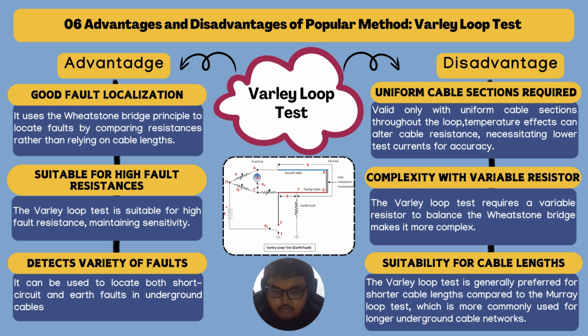The method had good fault localization, where we can locate the fault by comparing the resistance, despite relying on the cable length itself. The next one is the Varley loop test is suitable for high fault resistance that can maintain the sensitivity. And the last one is the Varley loop test can be used to locate two faults, which is short circuit fault and the earth circuit fault.